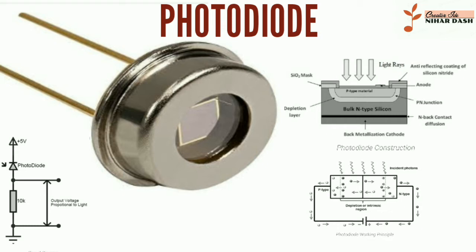The smaller end of the diode is the cathode terminal, while the longer end of the diode is the anode terminal. See the following schematic diagram for the anode and cathode sides. Under the forward bias condition, the conventional current will flow from the anode to the cathode, following the arrow in the diode symbol. Photocurrent flows in the reverse direction.